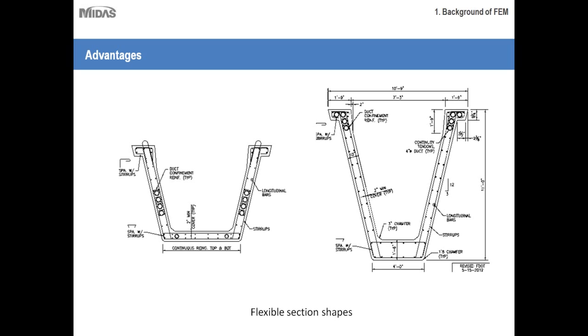And if you are doing the design check and you are planning to optimize the weight of the structure, then you can consider different alternates also. Based on the type of bridge you are doing, different span lengths and all, you can come up with a more optimal section rather than being limited to the conventional I section that we are using.